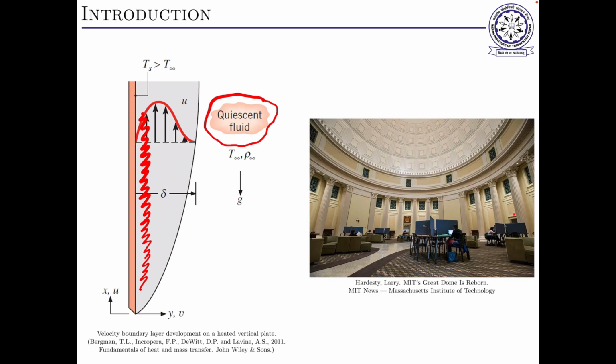In older times, when AC and all these heat transfer technologies were not so advanced, how did people have a cool environment and a cool ambience? The walls of the buildings were very thick, so the heat transfer from the sun's rays was slowed down, and the height of the buildings was very high. In old movies, old places and old monuments, you can see the height of the buildings is very high. Indoor heights are very high. There is a reason: the higher the system is, the density change will have a larger place to play, and the natural convection will be more effective.